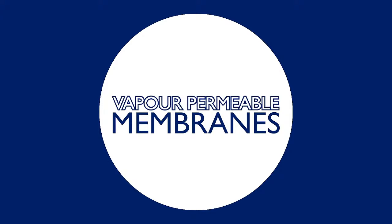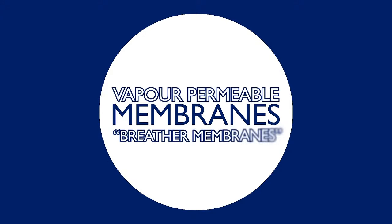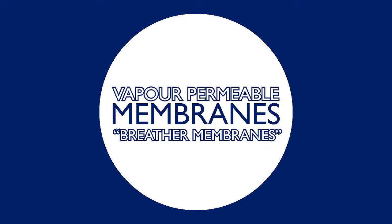The other type of membrane we'll consider today are the vapor permeable membranes, sometimes referred to as breather membranes. In contrast to AVCLs, vapor permeable membranes allow the passage of moisture vapor, but are usually also resistant to liquid water. Depending on the membrane, they can also be airtight or air open.